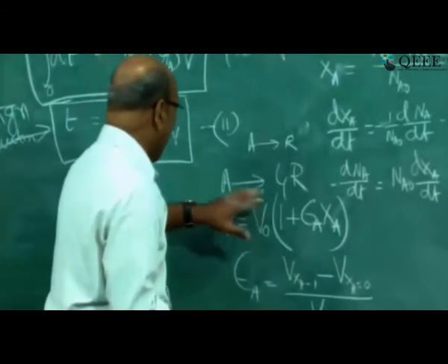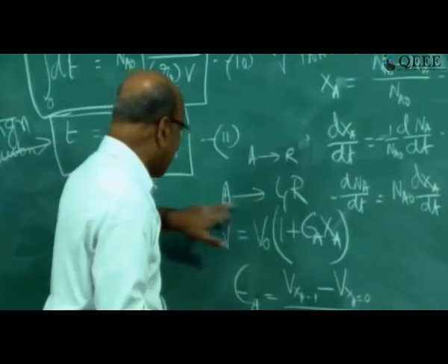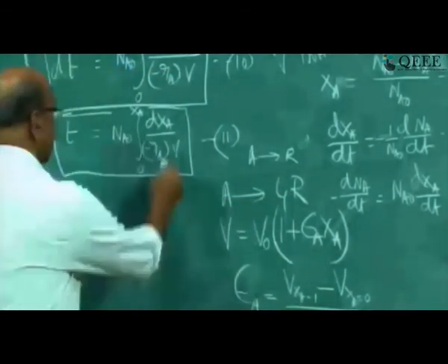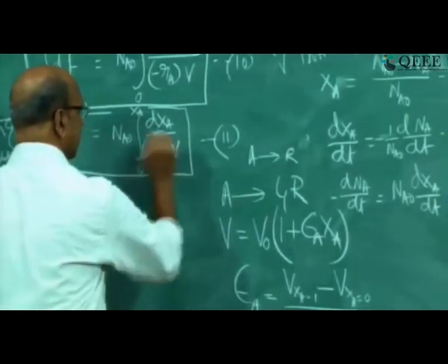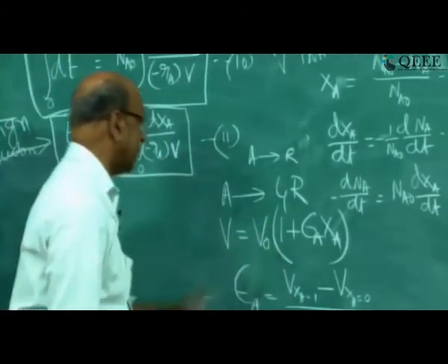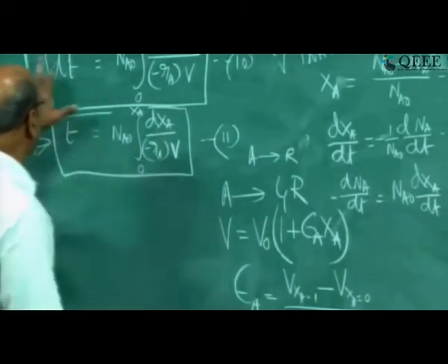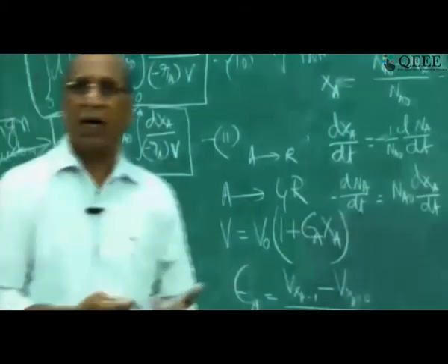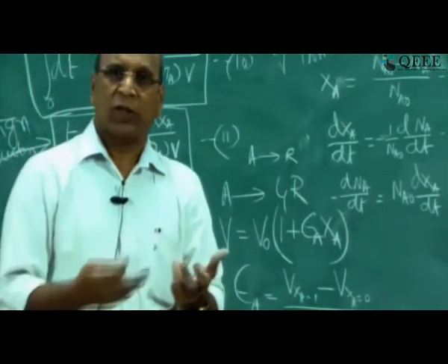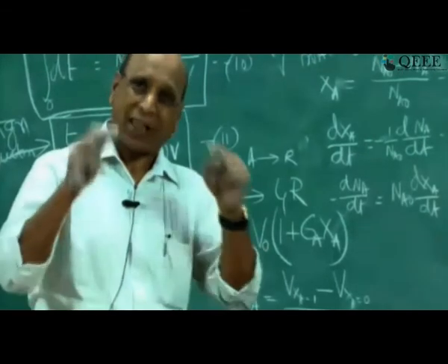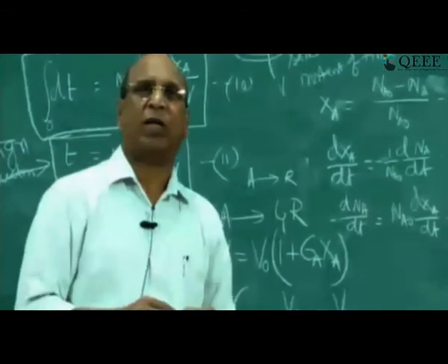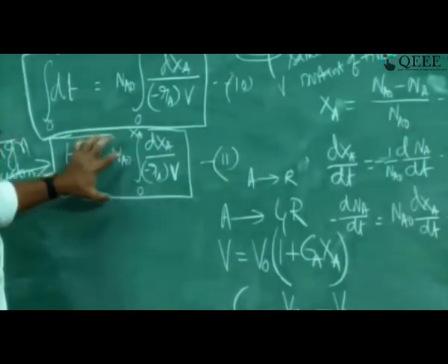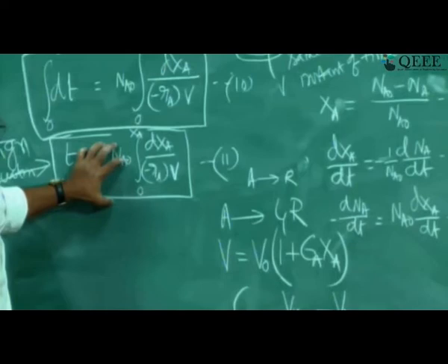So that is the reason why, depending on the stoichiometric equation, we have this epsilon coming into the picture, where this V is defined like this. This V is the volume. But actually this is for isothermal conditions only; we are designing only isothermal. If it is non-isothermal and the pressure is changing, then we can also derive that equation. That equation I have, but unfortunately I may not have time to derive all that. Okay, so this is the design expression for the batch reactor.